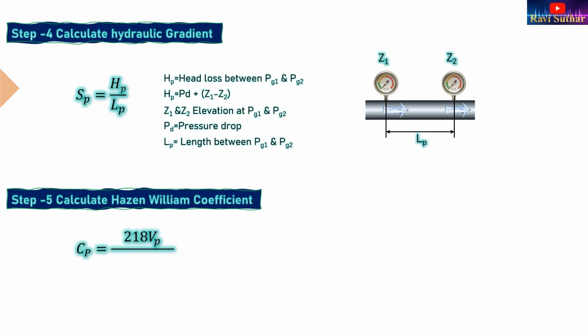This is the formula to calculate the value of the Hazen-Williams coefficient. Whatever value we get from this formula, we have to put into the water supply distribution model where we had used the theoretical value. After putting in these values, we have to find the pressures at the different nodes and calibrate the water supply network model accordingly.